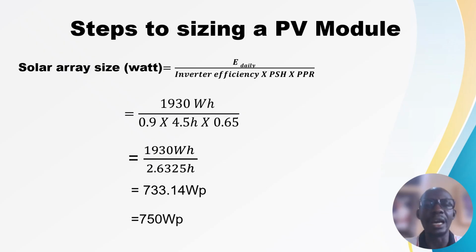And the PPR is panel performance ratio. You are not to expect your panel to deliver its maximum power. You get it? It cannot deliver its maximum power, and we agree that okay, 65%, it will deliver 65% of its power.